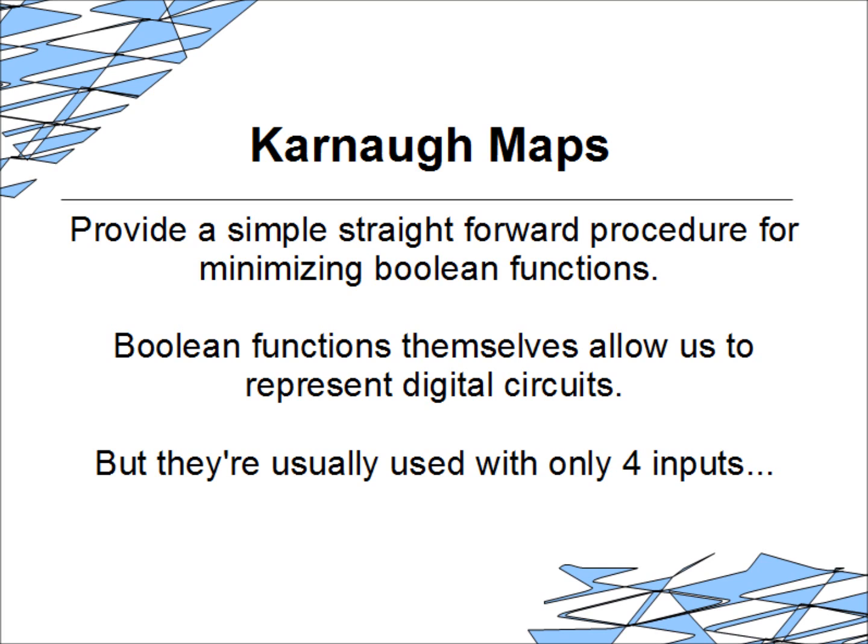Okay, we won't touch all possible digital circuits. We're just going to consider combinational circuits, which are circuits that only care about what's happening in this instant rather than what happened in previous iterations. There's no sequences, just circuits of addition, arithmetic operations, conversions, and such kind of circuits. Now, Karnaugh maps are usually restricted to 4 inputs, and in this particular video, those are the Karnaugh maps we're going to be talking about, just to make sure that we're all sharing common ground, and to help out those guys with the homeworks and problems to understand this stuff.